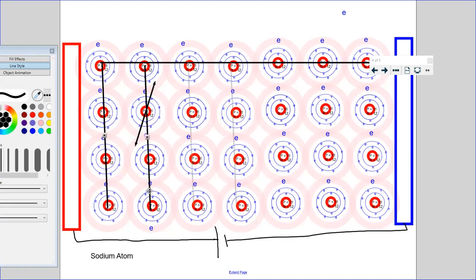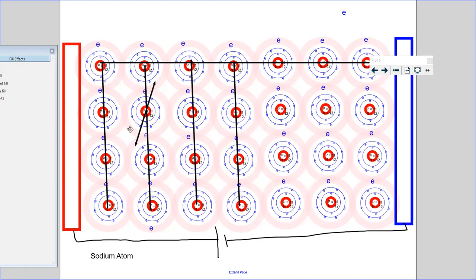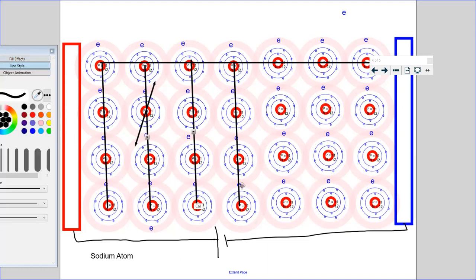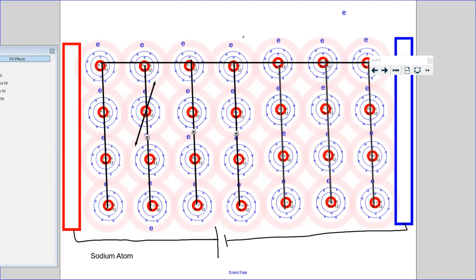Oh, sorry, with the free moving electrons. This lattice, okay, call it lattice. This is the reason: collision of the electrons with the atoms in the lattice causes resistance. More the collision, more the resistance. Less the collision, less the resistance. And that collision is due to vibration.